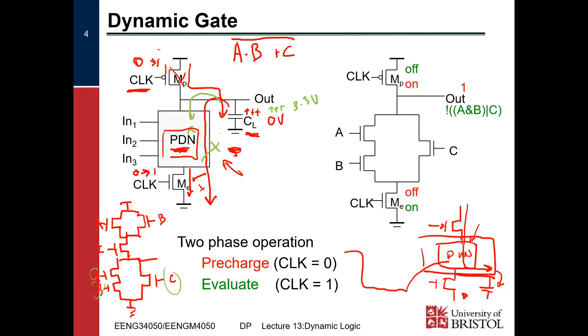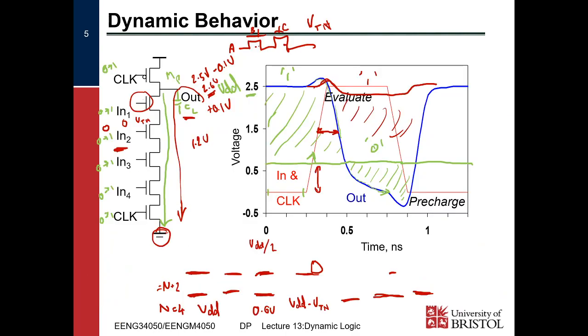Yeah. Well, the second one reduces the power consumption. Because with this one over here? No, because actually, no, let me think about that. So the static components aren't massive in dynamic logic generally. Generally the biggest thing you are concerned about is the dynamic power, because the dynamic power is so high in dynamic logic.